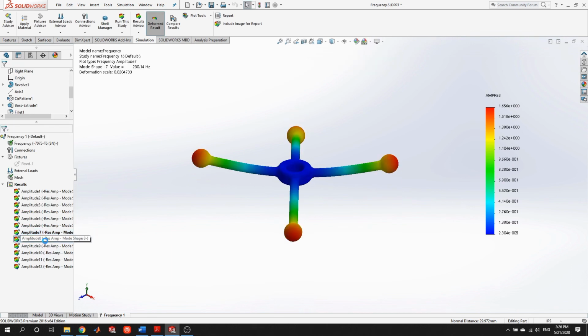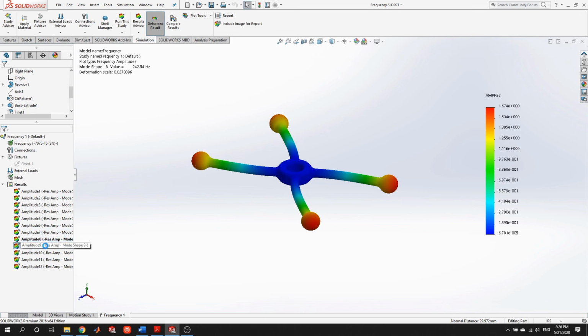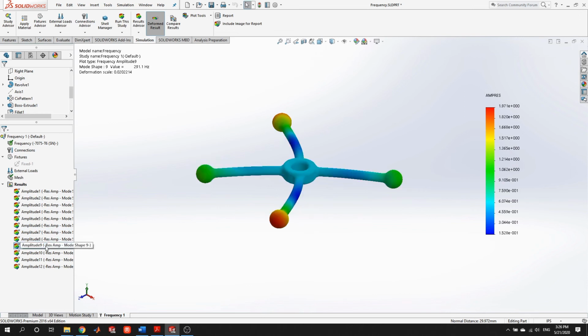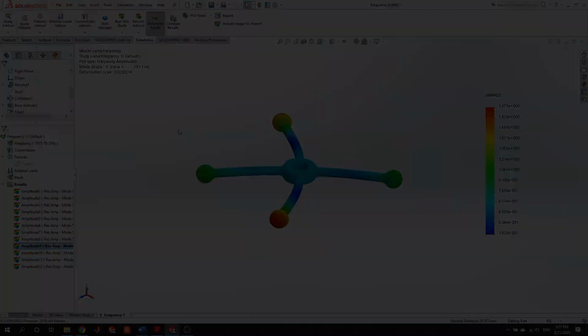And of course, as we go through, some of the modes look similar. The frequencies have changed a little bit. So by having the part restrained versus unrestrained, it does vibrate differently. And that makes sense if you've played with anything that vibrates, holding it against a solid surface maybe, and then vibrating it, or kind of understanding how it vibrates in space. But again, this frequency analysis is extremely important, especially when you're considering components that you expect vibrations in your part or that have other machinery, because again, everything vibrates, and this can be a critical failure if you're not careful.